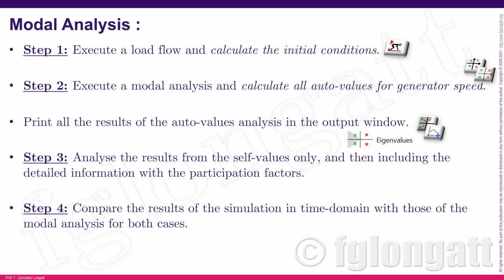The first step, especially if you are using the very old version of DIgSILENT PowerFactory, is executing the load flow and calculating the initial conditions, okay? If you are using the very old version of PowerFactory, for instance version 15.1, you must do this step number 1. If you are using the version 2021, no.